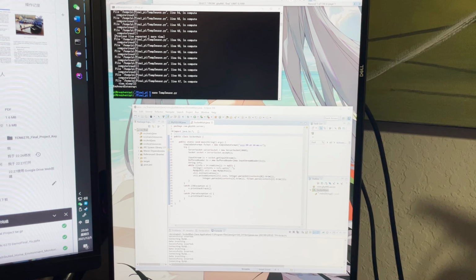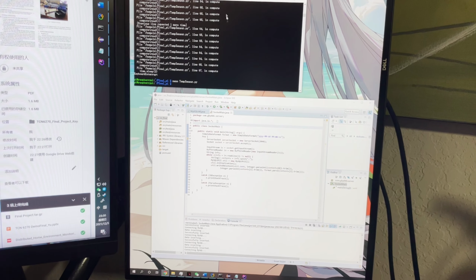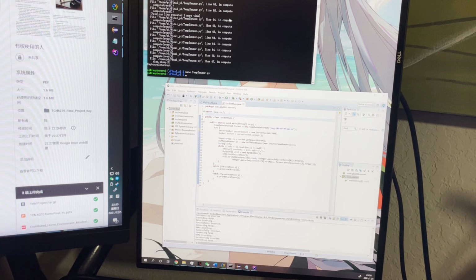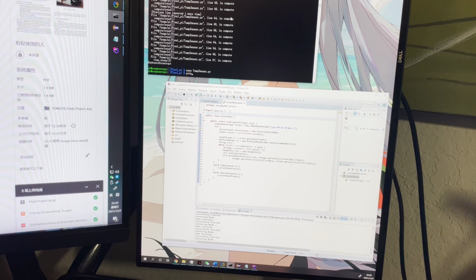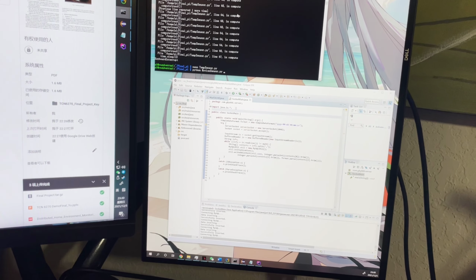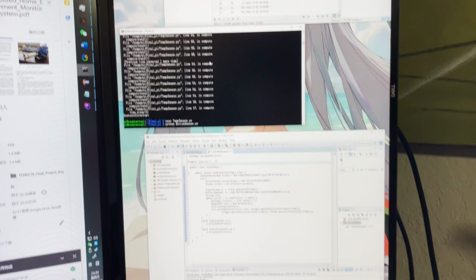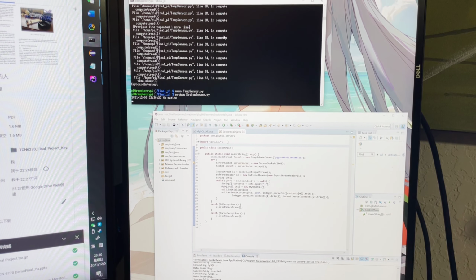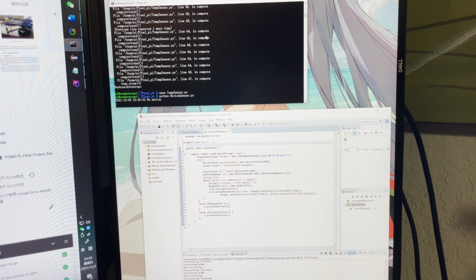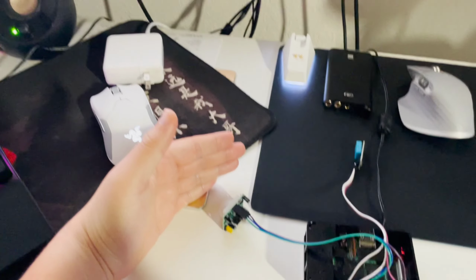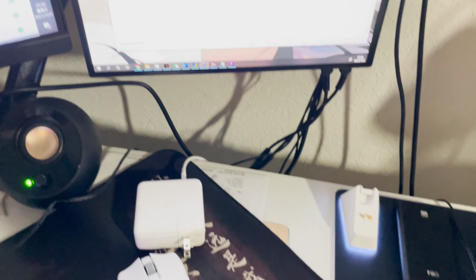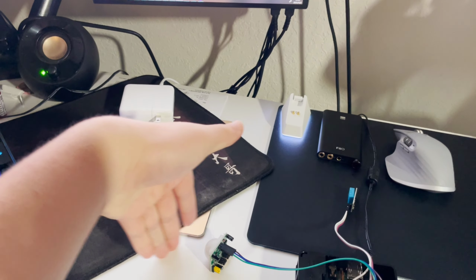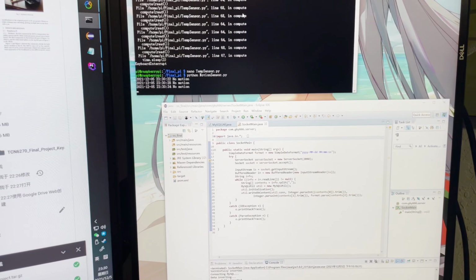We will first run the motion sensor part on the Raspberry Pi. We simply run python motion sensor.py. The default output is no motion, and if we put a hand in front of it, like this, it should give us is motion.